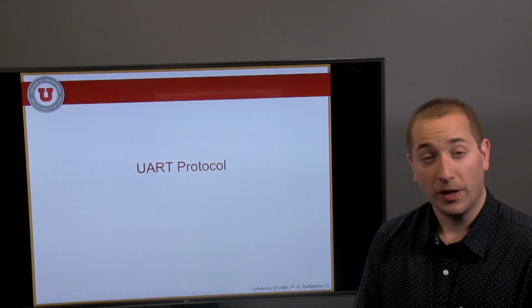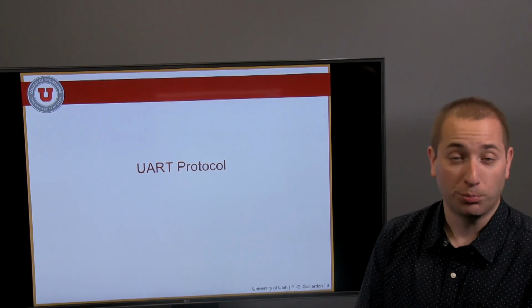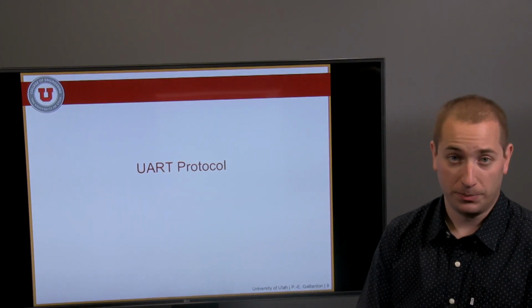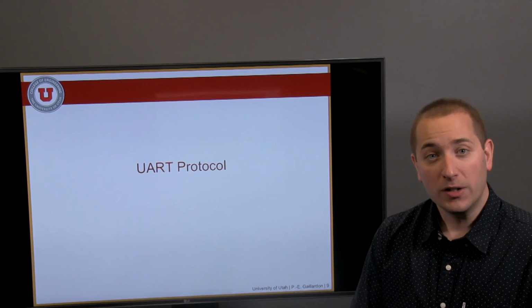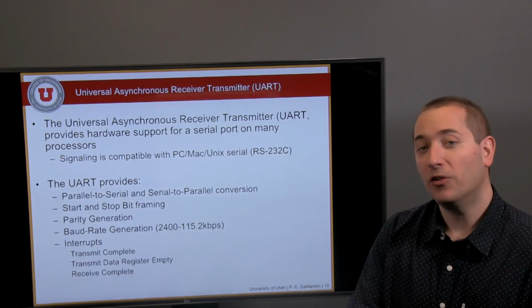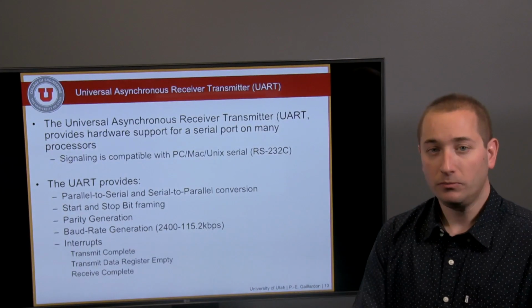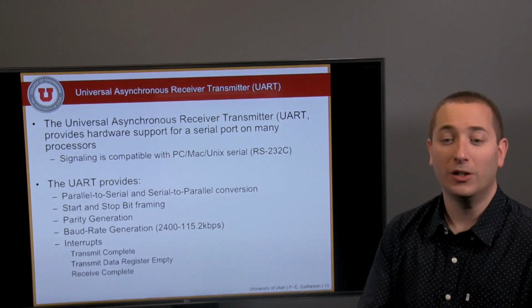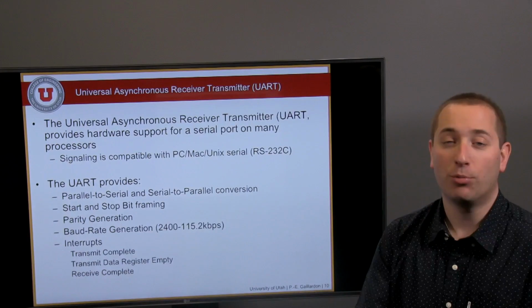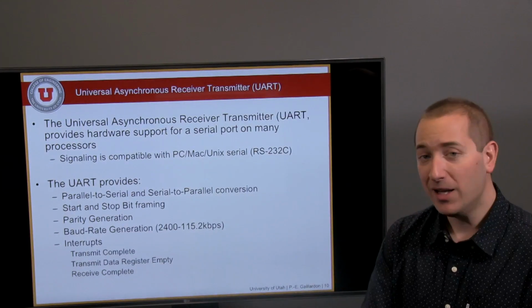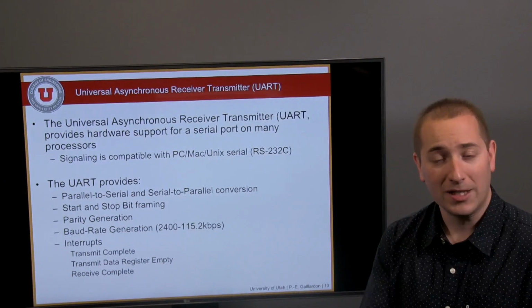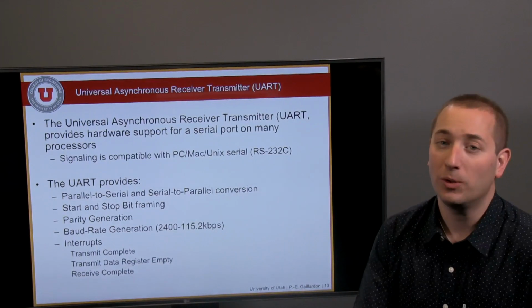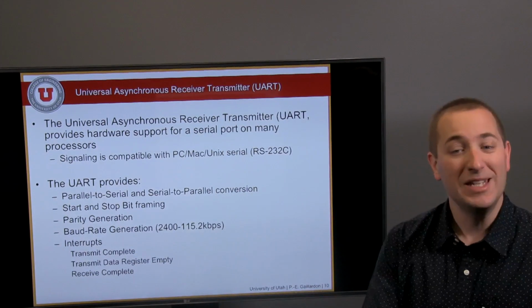The UART protocol is the simplest and one of the most used protocols you can use in your microcontrollers. UART stands for Universal Asynchronous Receiver Transmitter. It is designed to be a hardware module that provides support for serial links, serial ports on many processors. It is compatible with the RS-232 format that was traditionally used to create a serial interface on PC, Mac, or